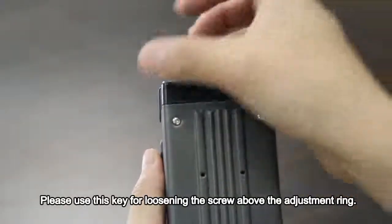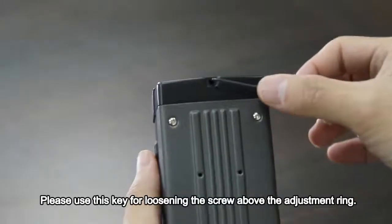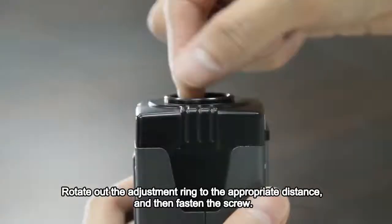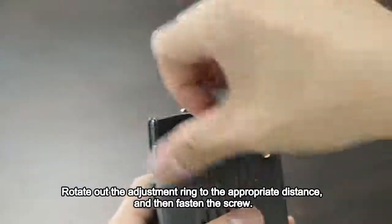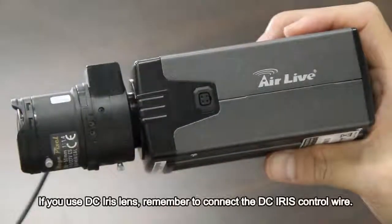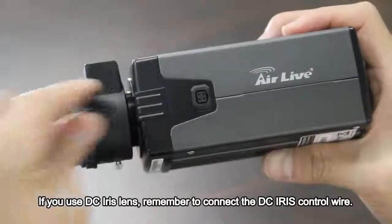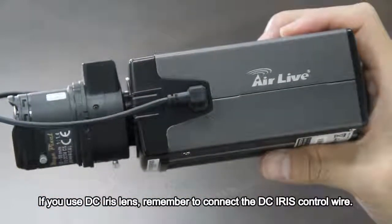Please use this key for loosening the screw above the adjustment ring. Rotate out the adjustment ring to the appropriate distance and then fasten the screw. If you use a DC iris lens, remember to connect the DC iris control wire.